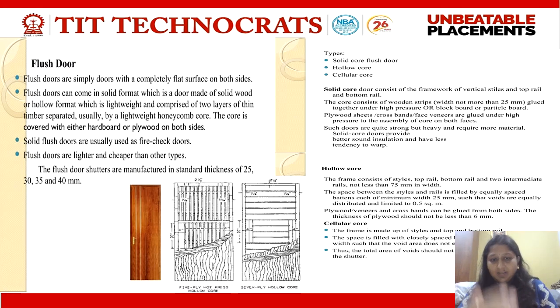Okay, all these inner thick plywood layers are covered with thick ply sheets or vinyl sheets, etc. Okay, they are covered with hard plywood, or with different varieties of designs nowadays, to cover this thick, huge single piece member of wood. Okay, a flush door may be of solid core or hollow core. Here you can see this is a solid core member. These are the hollow core flush doors.